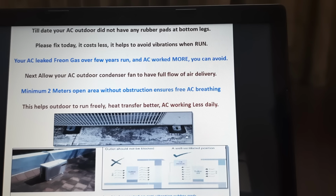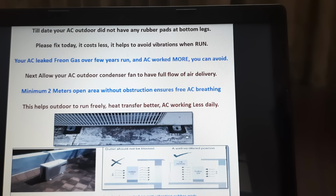Till date your AC outdoor did not have any rubber pads at the bottom leg. You can just buy them from the market, make them into 4 pieces, and insert them at the bottom of the leg. If they are not there, the vibration will start, and over the years a minute leak happens and the AC compressor runs more. So you can avoid the leakage by fixing these anti-vibration pads, and do not allow your AC outdoor unit to vibrate.